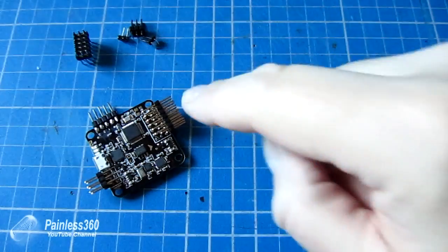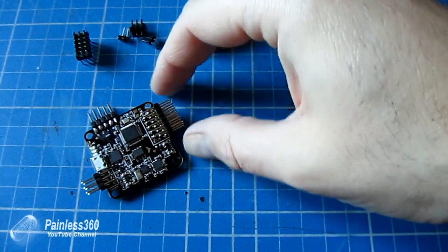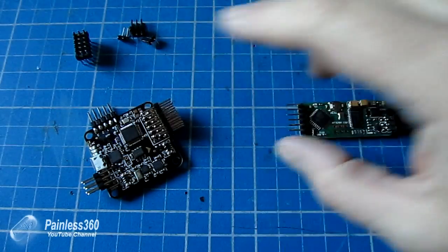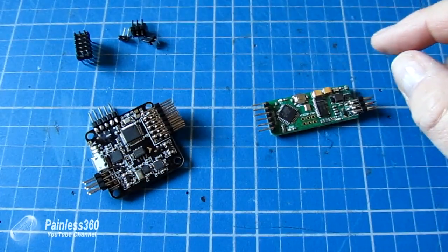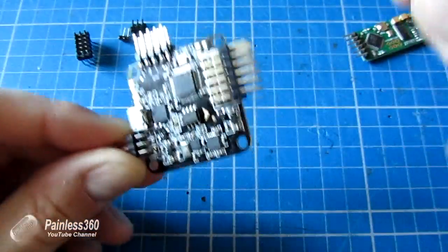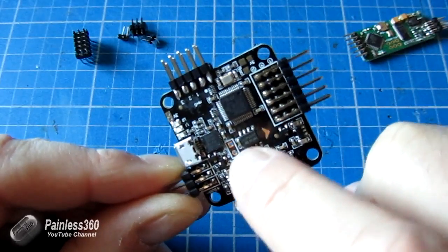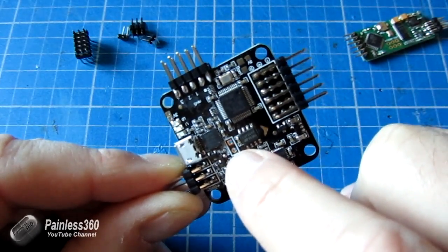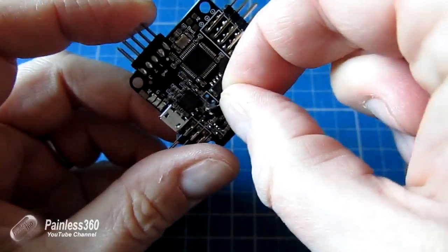You have to put these two pins in the middle because this is where the telemetry data is pumped out of the Naze32, whether you want it or not. You don't need to change any of the code on the Naze32 for this to work. It will automatically be sending out telemetry data via these two pins once they've been soldered on, and those two pins then become vital in how we connect the MinimOSD to the actual Naze32 itself.